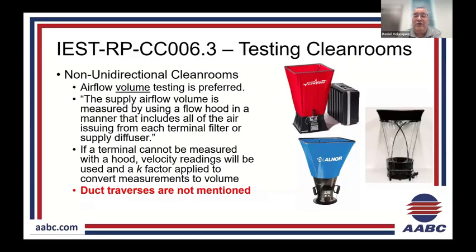So if you can't fit a hood on there, because a lot of times you go to these rooms, they may not have the highest ceilings. They got a lot of production equipment, filling lines beneath the filters where you can't get a hood on. That's when you have to use, recommended, either a Velgrid or a hot wire to get velocity readings and make a K factor to convert that velocity reading to volume. When you report